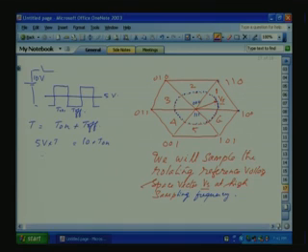So 5 volt is equal to 10 into T on by T. T on by T is called the duty ratio. By using this volt second balancing, we can generate the average 5 volt. So 5 volt will come chopped, then after this you put the filter and you will get 5 volt here. Filter means harmonics you can remove and the DC value you can generate.